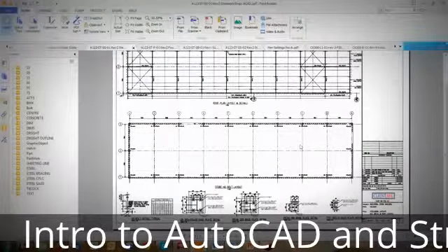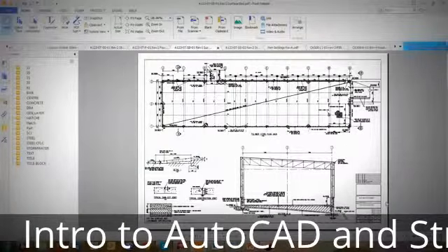Often mistakes are made, or often drawings are not done well, and it takes experience to know what contractors need and also what can be done wrongly, what can be done simply, and also how you're going to build this thing. How do you produce this in such a way that the contractor or whoever it is can actually build it? And also you must remember, these drawings don't just go to the contractor. They might go to the client, to the council for approval, and all those things. So you need whatever information is required for the different parties to use it.